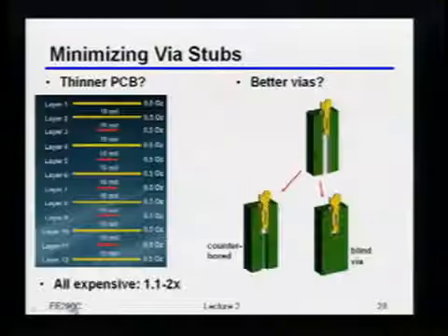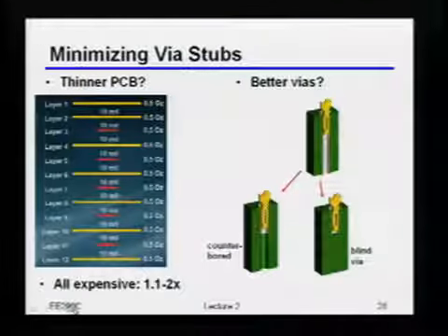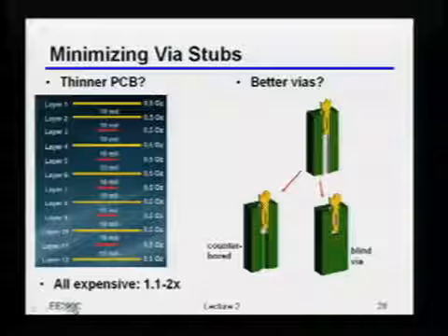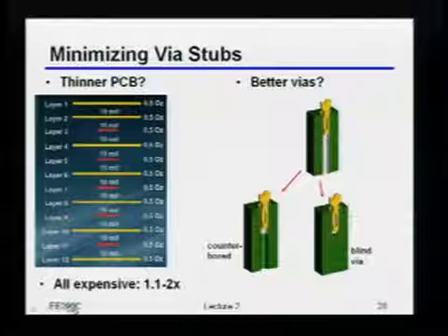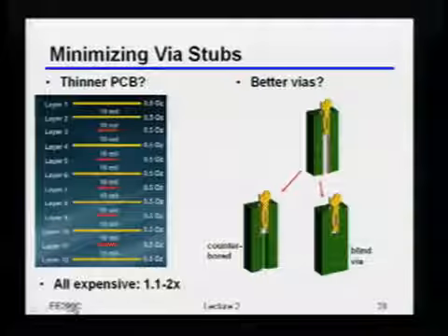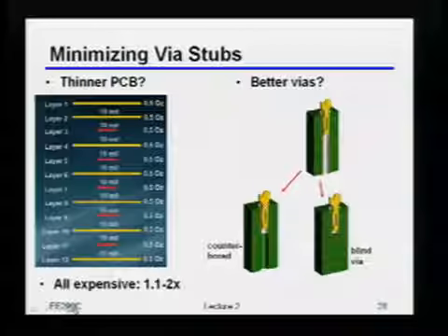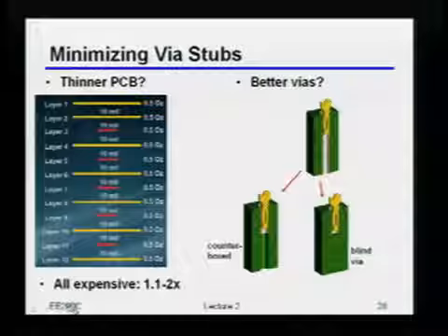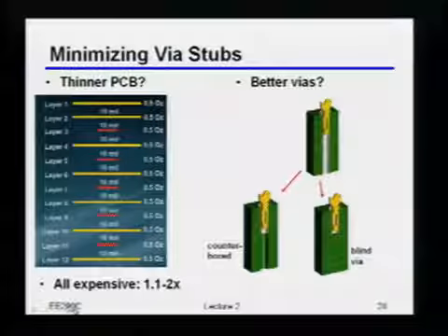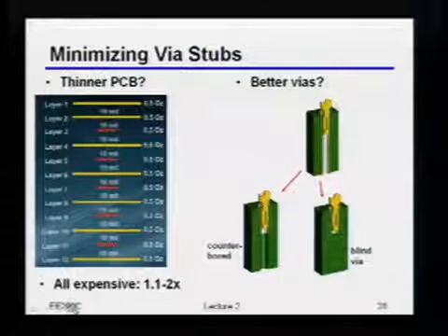So you asked the great question, which is, what can you do by design to make things better? I've given you a couple of options here. The first one is, how about we just make the PCB thinner, right? So that stub gets shorter and we push that notch out to higher frequency. Conceptually, great idea. What's the, let's say, minor practical problem? What do you guys think? Why doesn't everyone just make super thin PCBs? It's not as stiff. Yeah, it's not as stiff. I've got this 40-inch thing with God knows how much weight on top of it, right? Anything else?